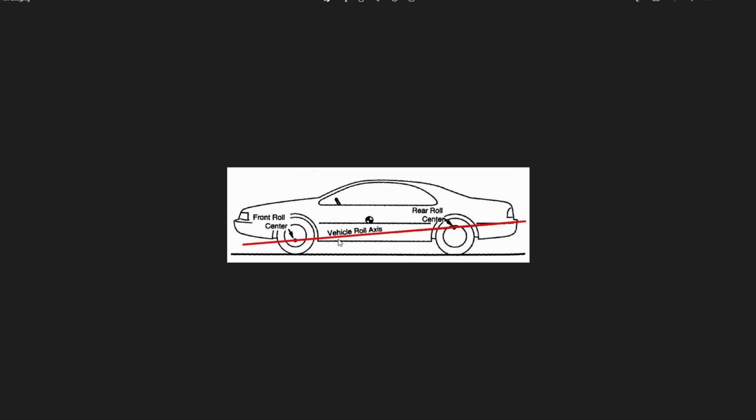Well, let's say you haven't angled it too much, so you went in smooth, then mid-corner the front has good grip, turning the car, the rear loses a bit of grip, allowing the car to rotate. Then you get on power. When you get on power, you want the rear to grip. You want the car to accelerate straight. With a high rear roll center, you get on power, load transfers quickly. Again, you have good initial grip, right? You are straightening out. You want the response of the rear end to be quick, the load to transfer quickly. And that's exactly what a high rear roll center does. So in this situation, I think that having the roll axis this way is beneficial.